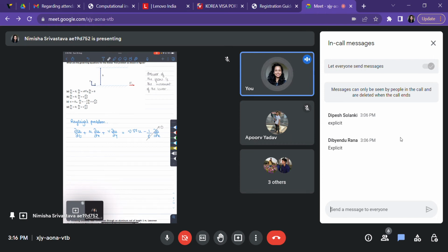du by dt is obviously going to be there because it keeps changing with time. But for du by dx, we are saying there is a fully developed flow, and there isn't any variation in the profile in the x direction. That is, in this direction there is no variation in velocity. This is also a requirement. So this goes to 0. Then v is equal to 0 everywhere.